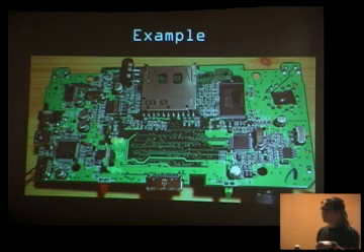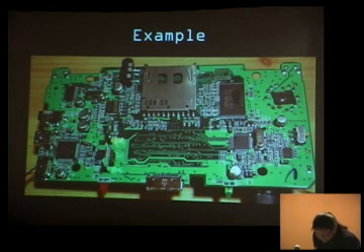Those big capacitors there, those are the bypass caps that sort of isolate the headphone voltage from the internal codec. That's the oscillator for the codec that sets the frequency. This is the SD card connector. This guy over here says NetChip on it, probably involved with the USB connection. I see an inductor here, and I see some other supplies here. This is the power supply, a local switching regulator, and so on and so forth.